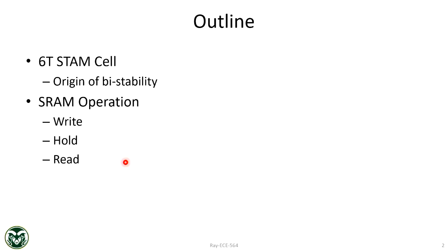Because during the hold period, if there is some bit flip, then it will be a problem later, right? Also, as we know, these days CMOS is quite leaky. Even if you're holding data, not doing anything, there will be a lot of leakage going on. So what can you do to minimize that? How will we optimize hold? Because it's not a non-volatile memory, you cannot turn it off. The moment you turn it off, things will be gone. So we'll see some of those things.